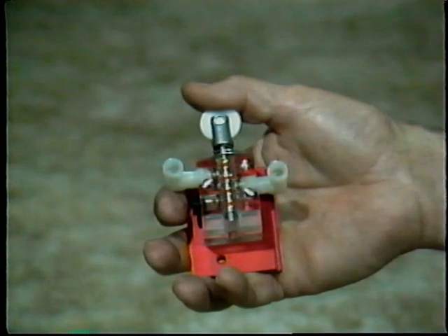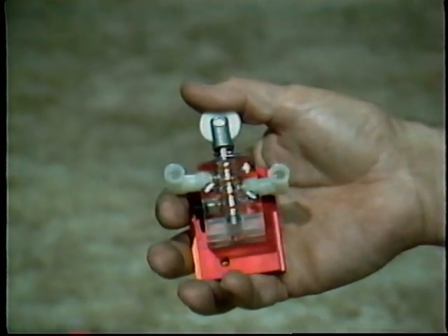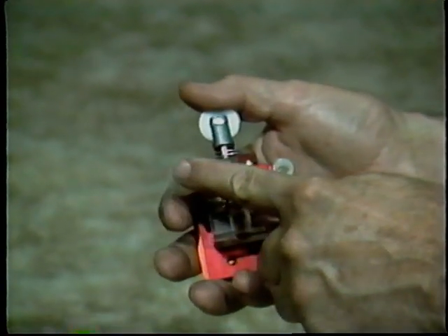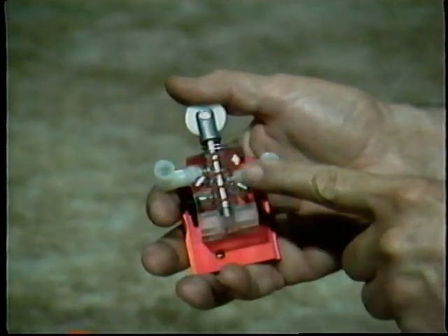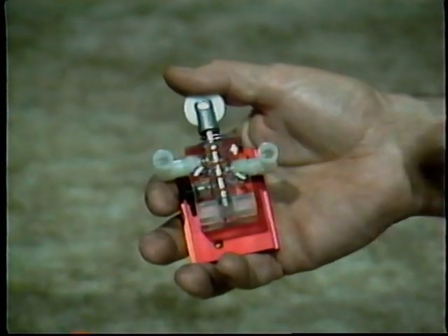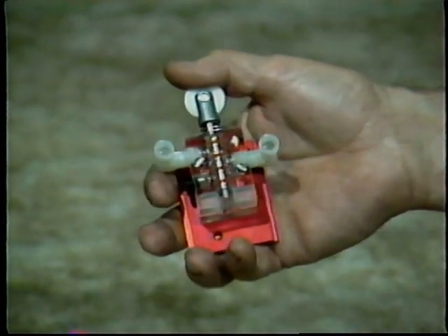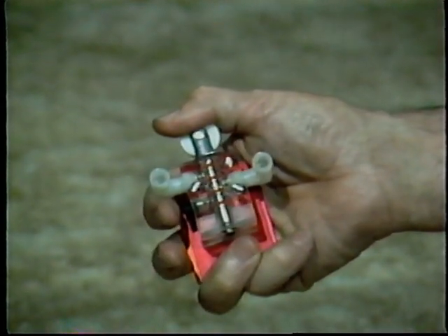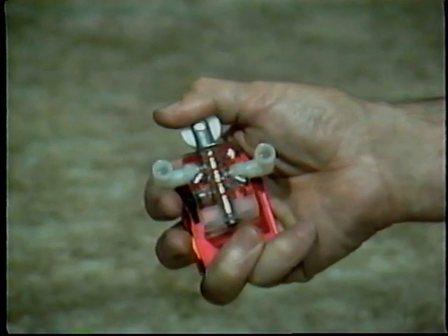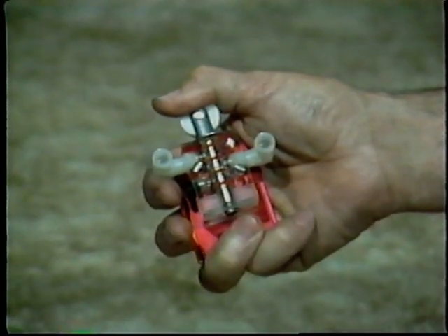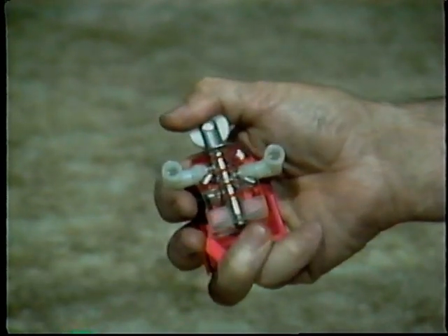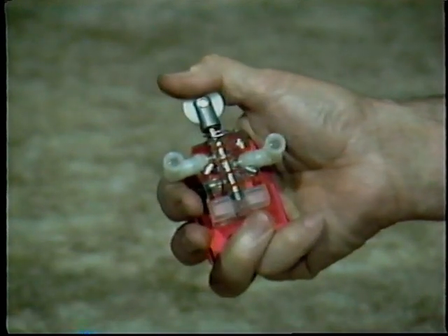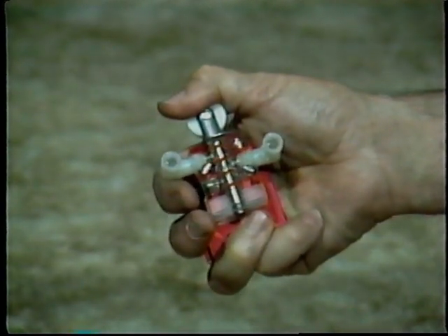When the valve plunger is at rest, as you see here, the valve allows airflow from here through the valve to this port. However, when the plunger is depressed, as shown here, the valve is closed and no air is allowed to pass. This technique allows us to control the airflow based on the position of the cylinder rod.